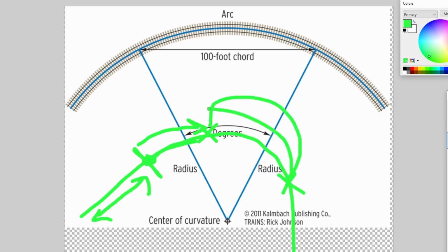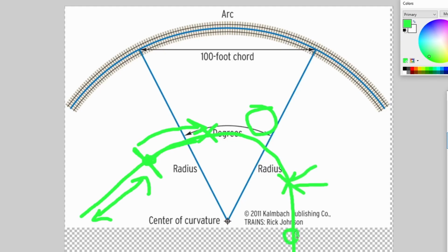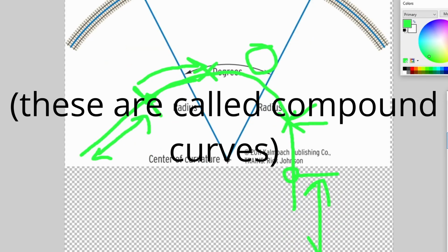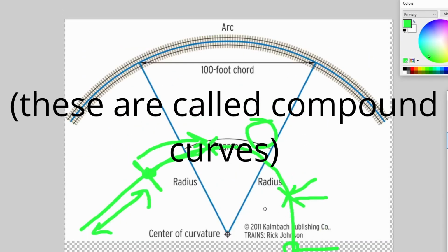This is all the same. So this is talking about it being a circle in here. And then again, we will have now a circle to spiral point on the back side, where we go back until we get back to tangent track once again. And that is the basis for most railroad track geometries.